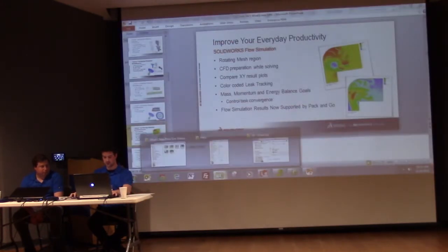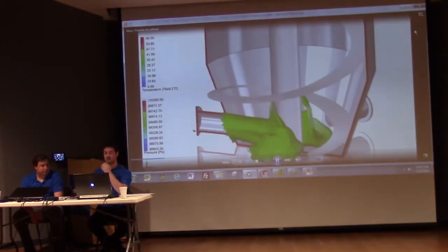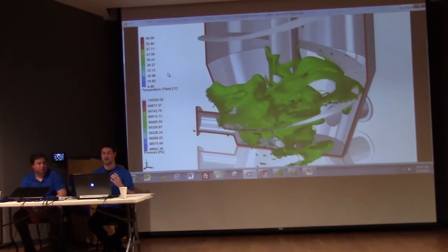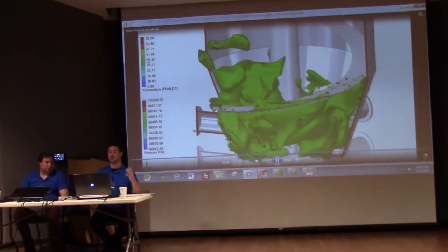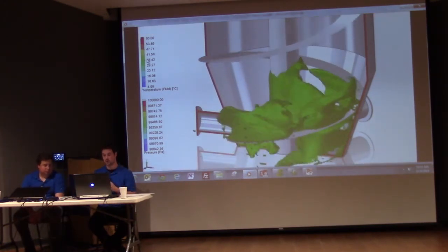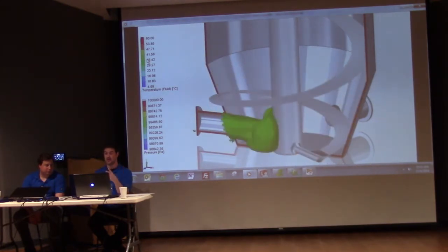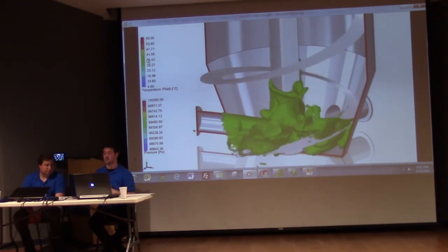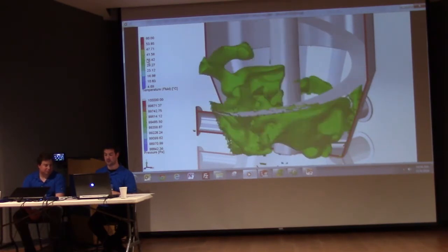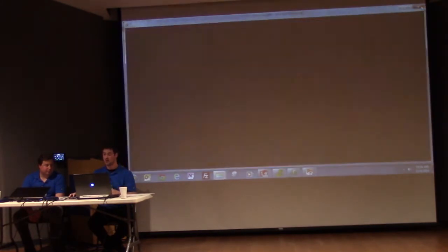So those videos I wanted to show our new rotating region. You can see here that as flow comes in, the green surfaces here are 30-degree fluid, so it's showing a 30-degree fluid coming into a warmer fluid, and you can see that the mixer is actually rotating and moving up. So you can see how fast this fluid will cool off by running this transient study here.